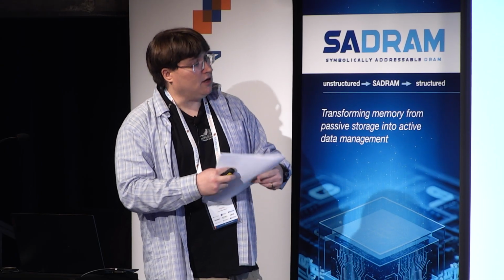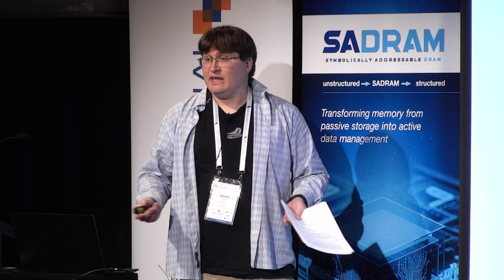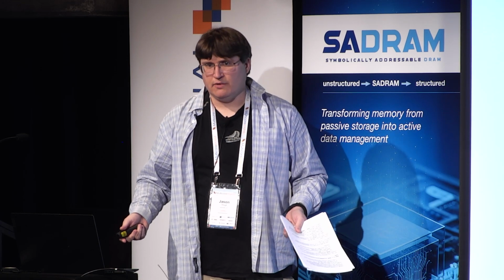All right, so originally we conceived of SADRAM as existing in DRAM slots. We want to take advantage of the fastest available connection. For our first prototype, we're talking about being in a PCIe slot hooked up with a CXL protocol. CXL gives us a data link, and it also gives us a configuration link, because we need to be able to define where the key is within the record. We also need to be able to find what kind of data it is, because SADRAM only really sorts data lexicographically, so A before B, B before C, etc.